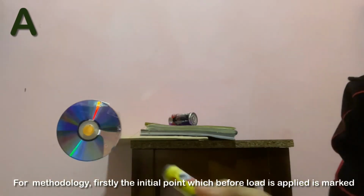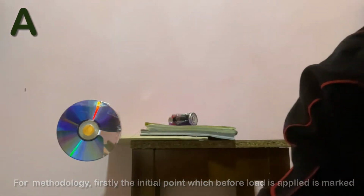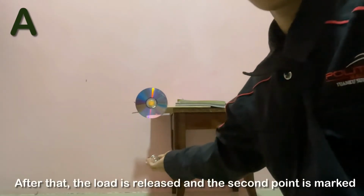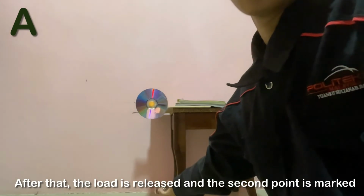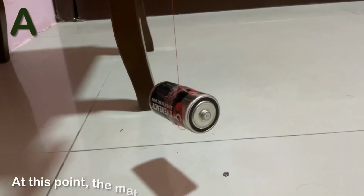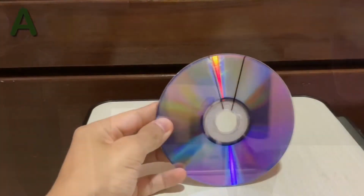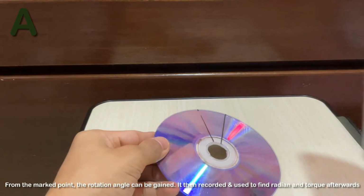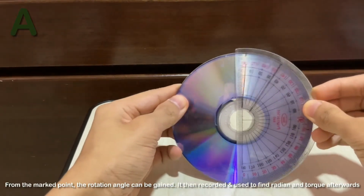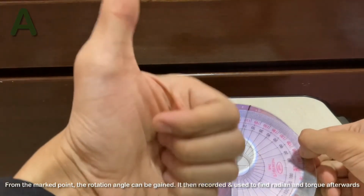For section A methodology, firstly, the initial point which is before the load is applied is marked. After that, the load is released and the second point is marked. At this point, the material is twisted by the released load. From the marked points, the rotation angle can be gained. It will then be recorded and used to find radian and torque afterwards.